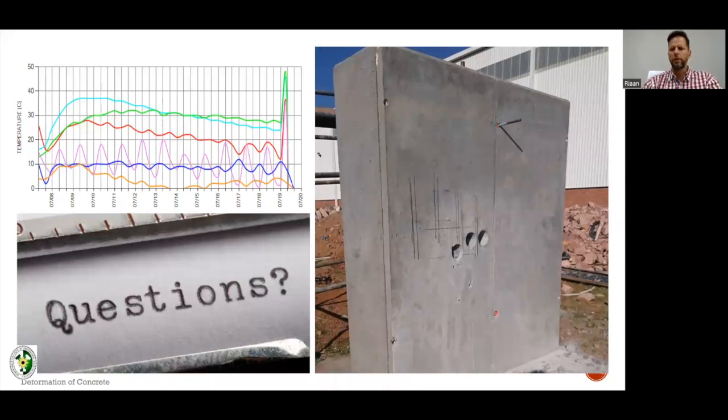So yes, you are right. In general, if you can end up with a more dense concrete matrix by applying a fit for purpose application, you cannot use a low slump concrete if you have very congested reinforcement. It will not move through your reinforcement. So that stands to reason. You'll end up with honeycombing and you'll be in a bad space if you've specified a low slump concrete for the application where you have very restricted movement of your concrete in terms of placing the fresh concrete.